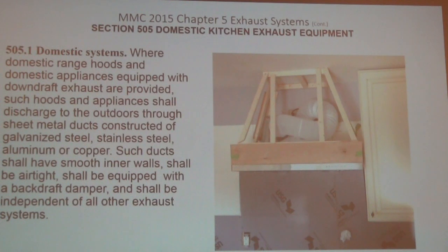It'd be a worse situation once the duct tape dry rots and the joint comes apart with not having sheet metal screws in it. So sheet metal screws are supposed to actually be in the duct joints of a domestic kitchen exhaust, if it's a round duct, because that's how the code is written. And that's my opinion. Like I said, a lot of these kits come with, have you seen it? It's like a white flexible hose. You go out on the job and they install it. Yeah, but that's what the manufacturer wants. So that's not how it works.